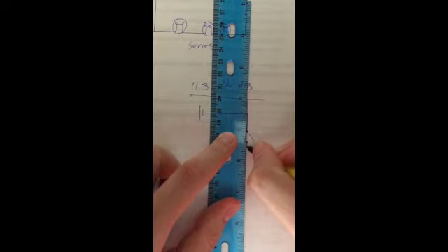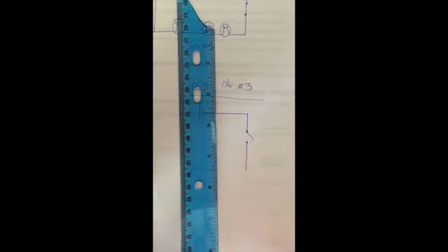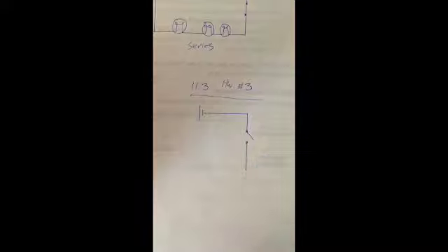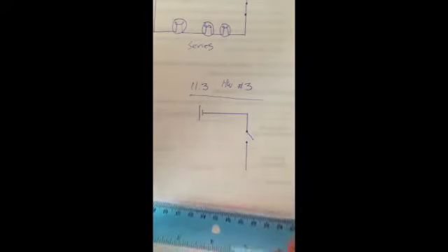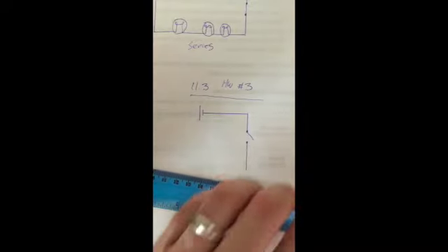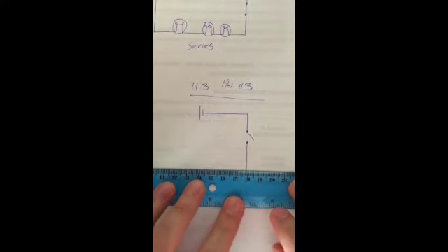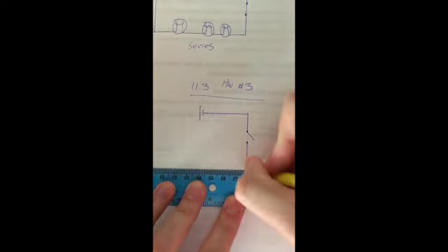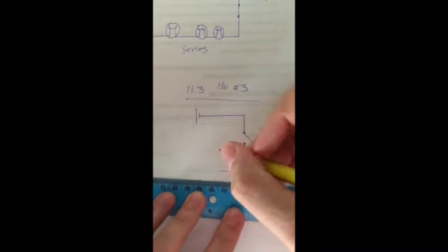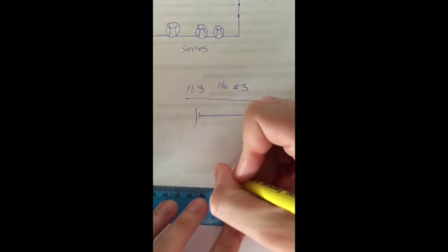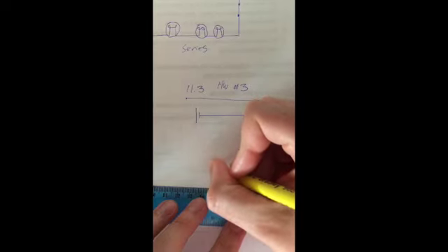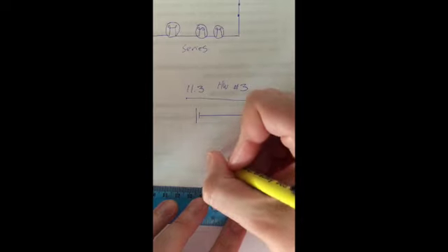And then let's continue down to the bottom. Now, our parallel bulbs are going to be a little different. So what I'm going to do is draw one bulb first, and then I'll show you how to draw the other ones in parallel. So just like before, we'll continue the wire because we do need a series pathway. Then we draw one bulb up here, which will be our main path bulb, and we'll do a circle around it.